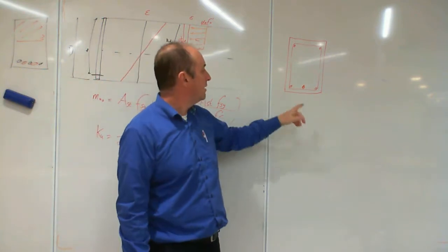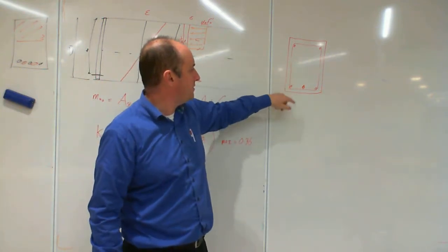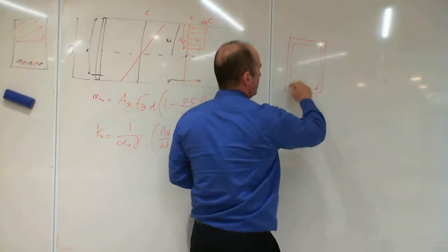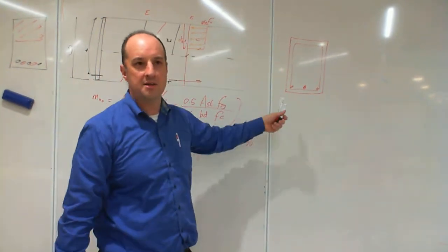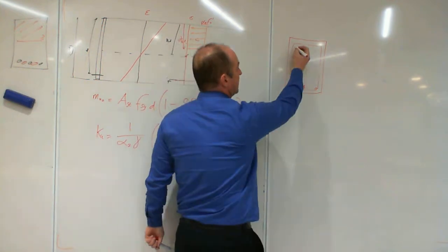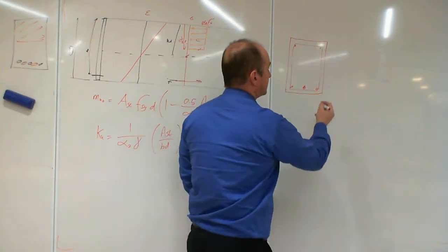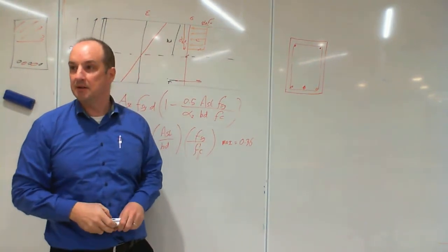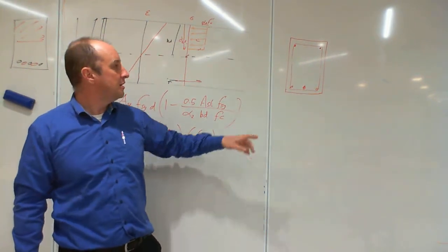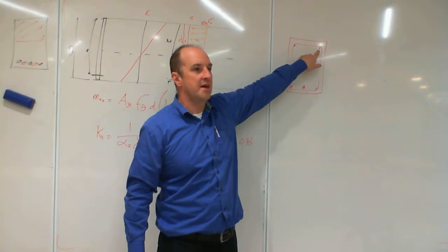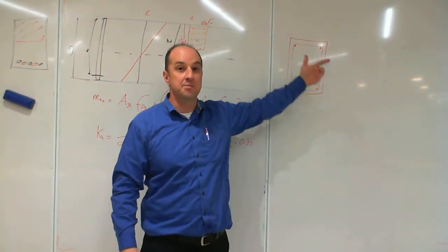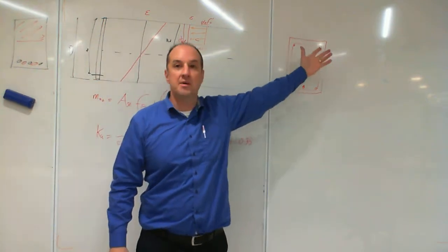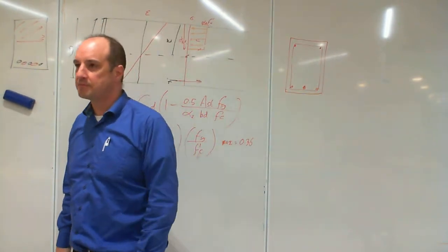Yeah. All right, now, if you design a beam without those, and you work out its capacity, and then you add a couple of small bars there, like that, you don't really change much in the way of bending capacity. You're talking a few percentage points. Those bars often are there just to hold the rings in place. Okay? The shear rings are needed. Those bars, you need something to hang the bars on. That's what they're there for.